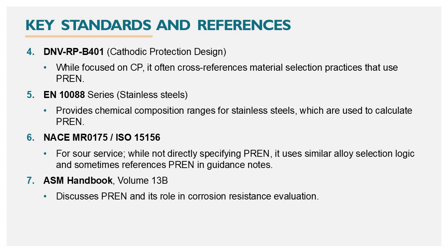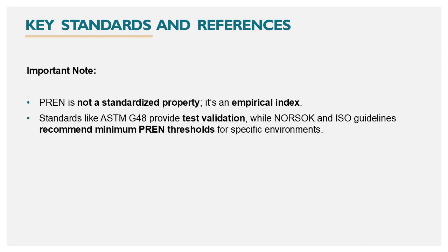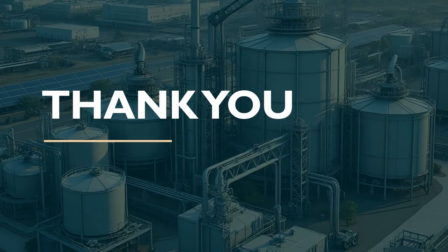It discusses PREN and its role in corrosion resistance evaluation. Important note: PREN is not a standardized property, it's an empirical index. Standards like ASTM G48 provide test validation, while NORSOK and ISO guidelines recommend minimum PREN thresholds for specific environments.